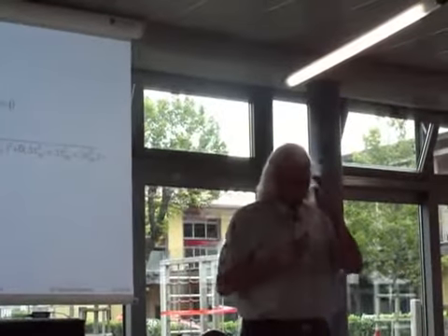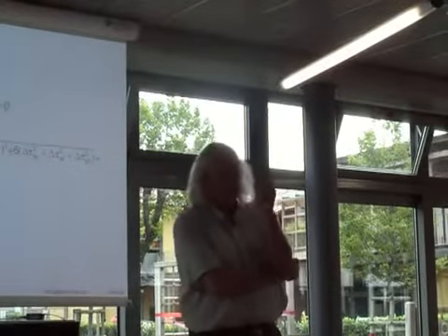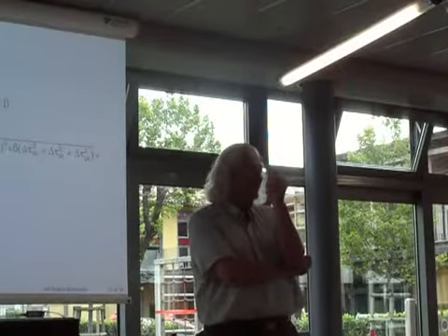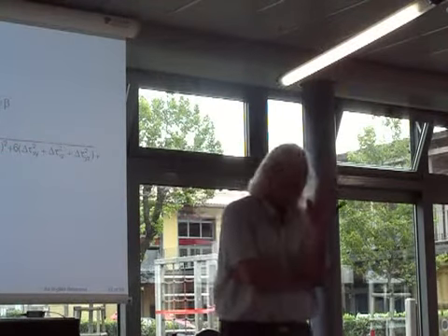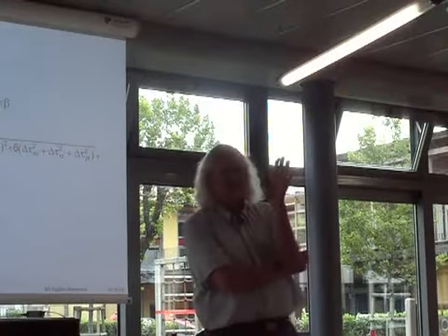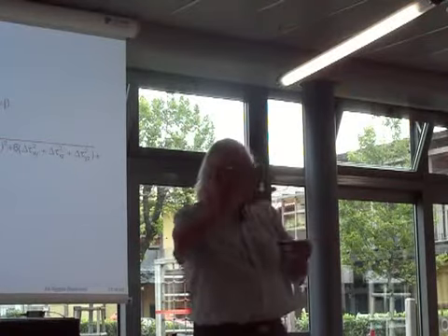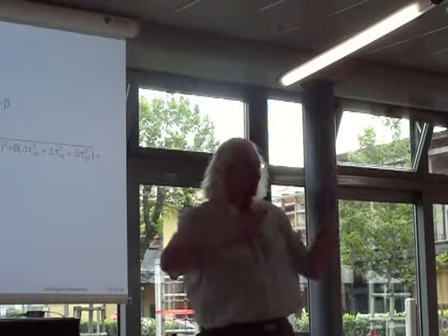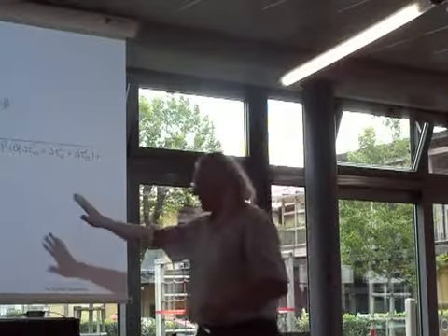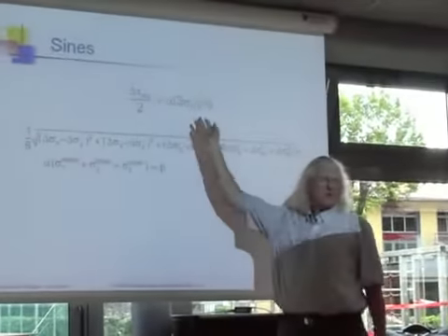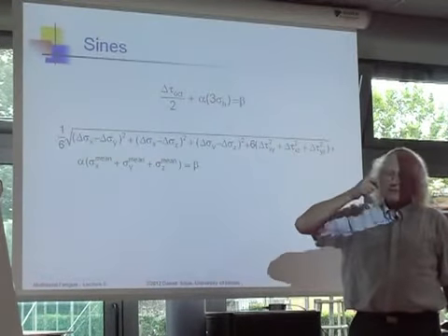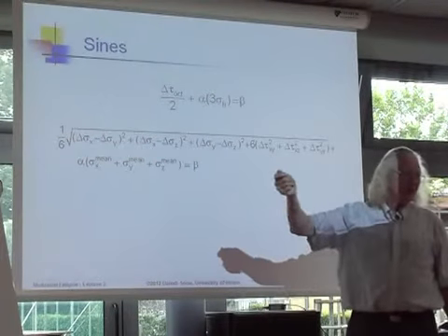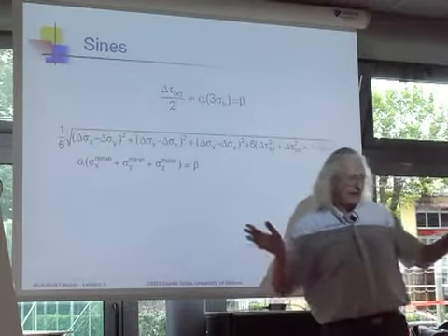Nothing more. And if you actually read Sines' paper, Sines tried several variations. He said, what if I use the maximum shear stress? And he plotted the data and said, oh, it's about the same. And what if I use the maximum stress instead of the hydrostatic stress? And he plotted the data, and it's about the same. And then after doing these different kinds of comparisons, at the end he says, I recommend this form because for a general stress state, it's the easiest one to calculate. It's not better than the others. It's not particularly worse than the others, but it's the easiest one to calculate.